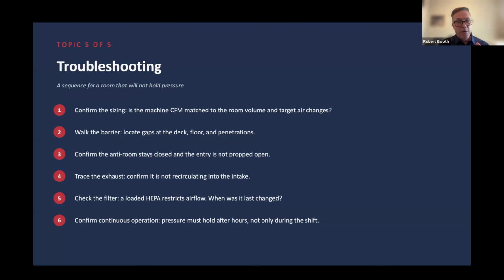And so I know I mentioned this, but you get a decrease, like Josh said, in efficiency of these HEPA filters from day one. And when we start seeing a decrease in desired pressurization, which also affects our air changes, everyone just thinks, well, the machine's running, but they don't look to see that maybe your static pressure increase is out of range and it's starting to get really loaded because of the things that you're doing to affect it. And that's really important.